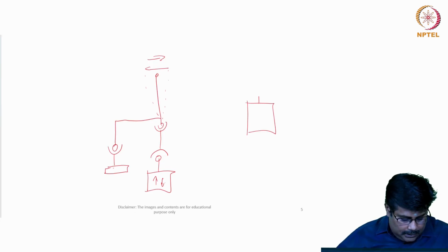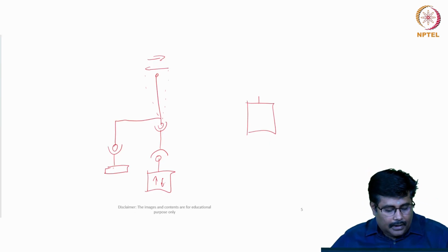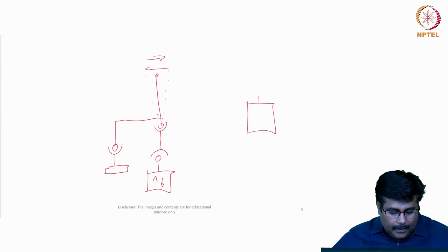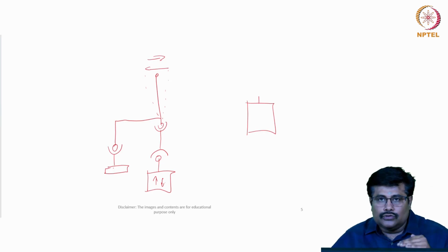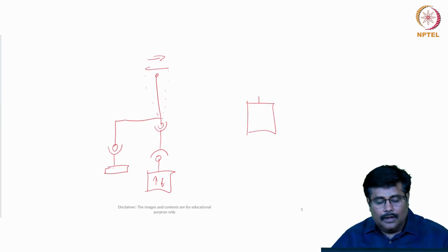So it is noted that to convert this into a linear motion, it requires a kind of a linear guidance. If the arm is long enough and the displacement is still small, the circular end effector motion can be neglected in the first approximation. So as far as this particular case is concerned, it's a kinematic of a bar with two pivots, which can be used to accommodate the linear motion produced by the linear guidance of the system with the angular motion of the lever.